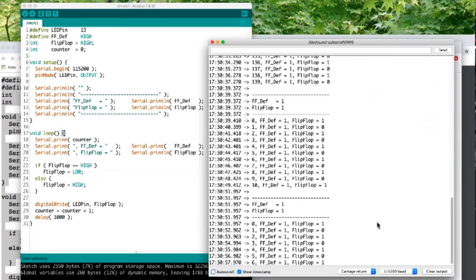My question is, when you push the red button, do you see this kind of display? Provided you have the baud rate set correctly to 115200. Everybody get it? Is everybody able to reproduce whatever we're doing?